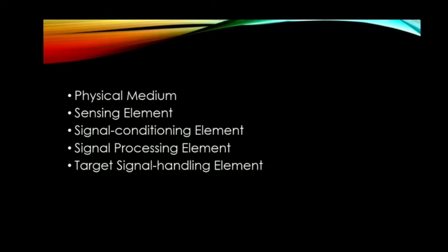These typically involve analog electronic circuits that finally produce electrical signals in the form of voltage or current in specific ranges. The signal processing element is used to process the signal generated by the first stage for a variety of purposes, such as filtering, to remove noise, diagnostics, to assess the health of the sensor, linearization, to obtain an output which is linearly related with the physical measure, and so on. Signal processing systems are therefore usually more general purpose in nature.